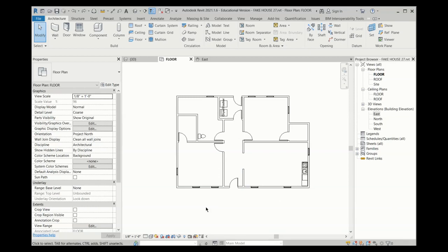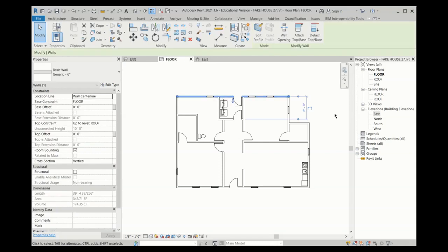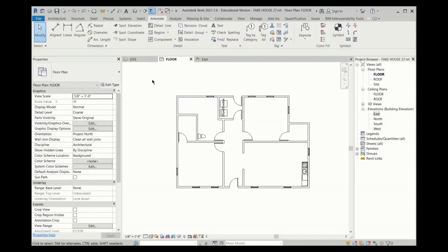All right, the next thing is we need to understand the square footage. There's a couple of ways you could do this. You could go into Annotate and use some temporary measurements using the aligned or the linear measurements. Don't leave them. If you use the measurement tool, just click delete on them when you're done. You could also click on the walls and it'll show you some references there. It's not very elegant that way.